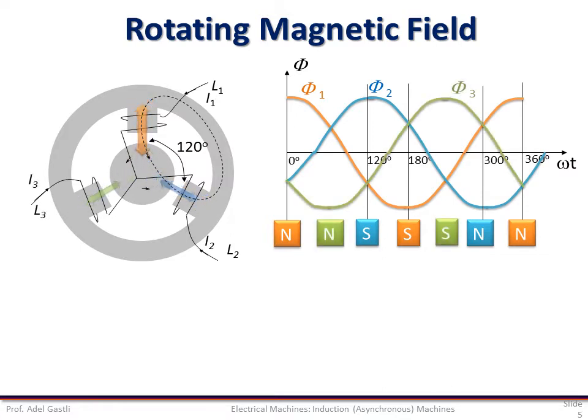When the third phase has been connected, there are three magnetic fields in the stator core, and there is 120 degrees displacement between the three phases. The magnetic fields of the individual phase windings make up a symmetrically rotating magnetic field called the rotating or revolving magnetic field of the motor.